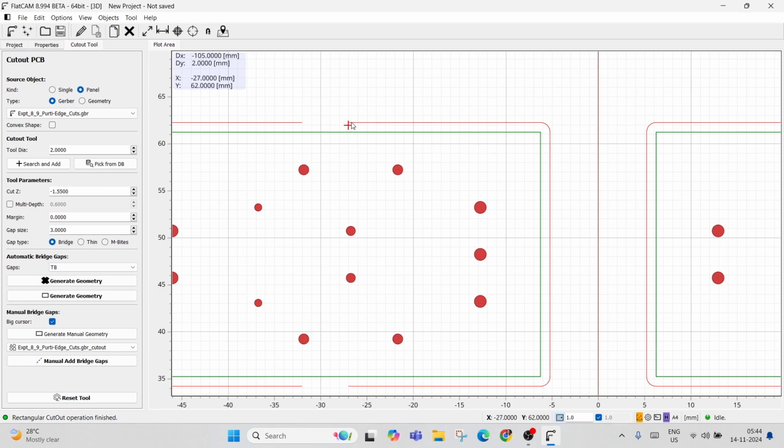Here it is not going to pass, so here the edge cutting is not going to happen, it is going to create a bridge. The drill bit is 2 mm in size, so 1 mm on this side and 1 mm on the other side, a total of 2 mm is going to be drilled away. Then we have so much gap in between, and then again up till here will be drilled away, so there is some support for the drill bit to drill.